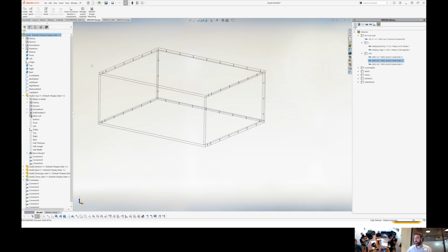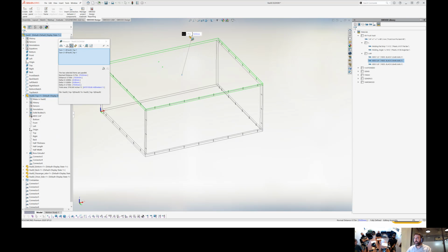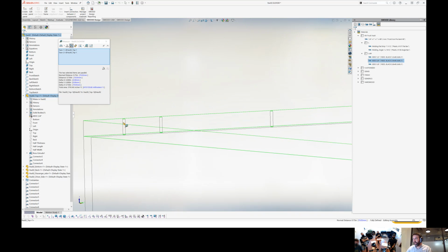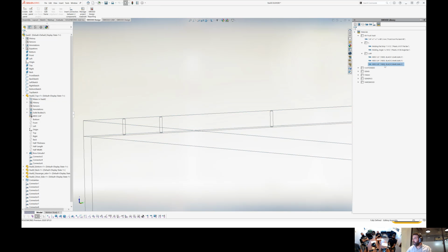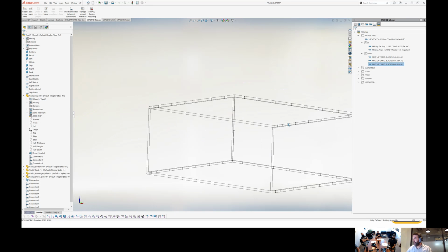So when I do that, I change my material in my SolidWorks part, but I'm also directly going to update the thickness of the panel with a new material definition. And of course, all the drillings will still be correct to go through with the new thickness. So if I do that again, we are going to see now here. Okay, so we change the thickness, but the drilling is directly adaptive with that.